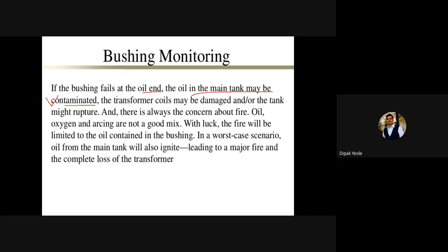The transformer coils may be damaged, and the tank might rupture. So you can see the bushing fails at the oil end. These are the reasons that can happen because of this bushing failure. And there is always concern about fire.